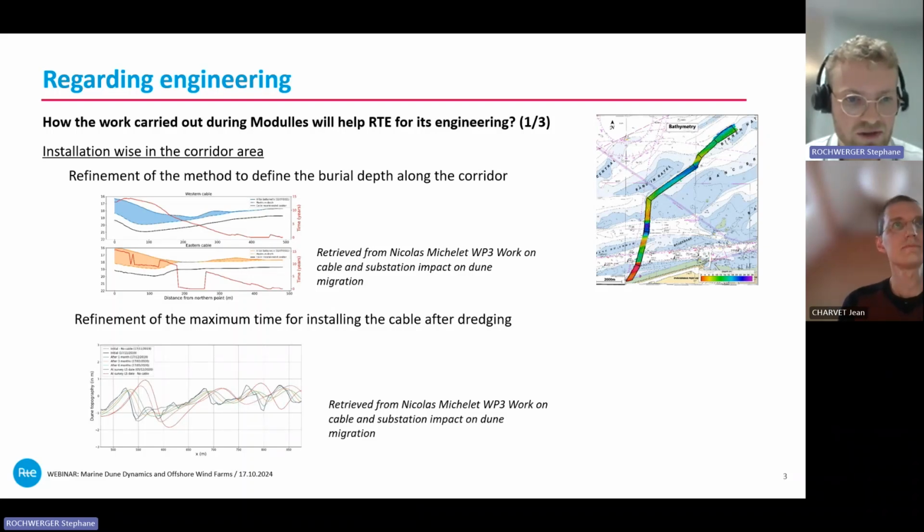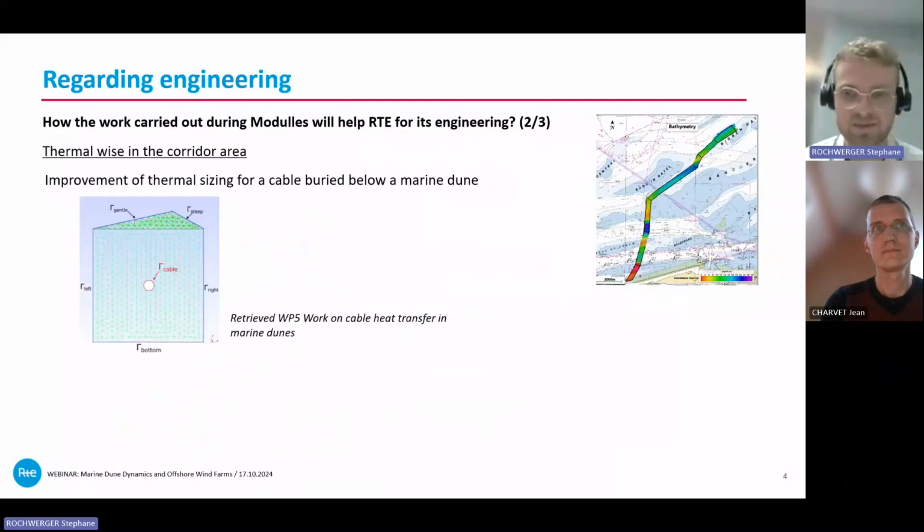Then he also focused on the dune recovery. After dredging, there will form, let's say, a small artificial dune, and how much time will it take to refill the trench? It's quite important for us because this time needs to be sufficiently long for us to install the cable, but not too long, because once the cable is installed, we need the cable to be protected by the seabed. So it's quite important to have a better understanding of this process.